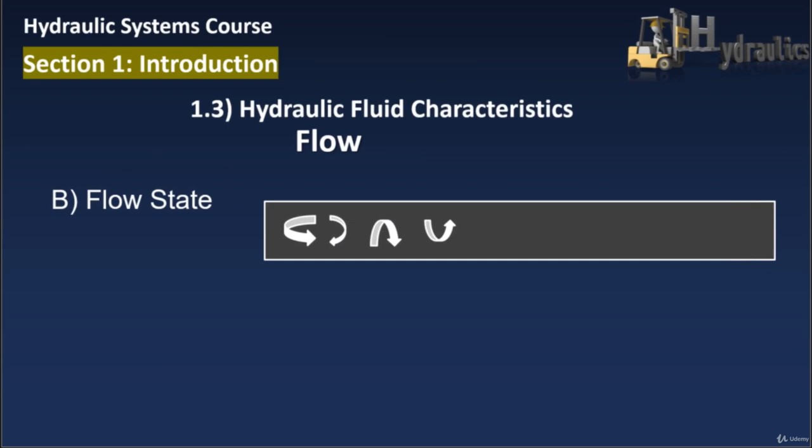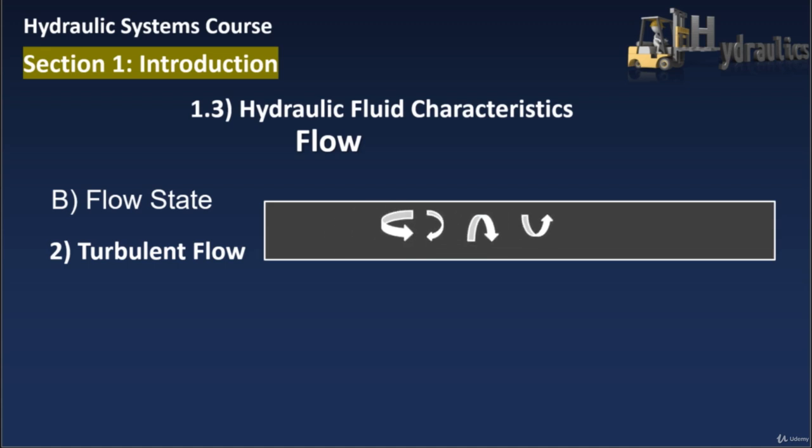The other type of flow state is turbulent flow, and in fact, hydraulic system flow often experiences more turmoil or disturbance than desirable. Although fluid generally moves in the required direction, it also travels through small conduits, cross-shaped restrictions, and small orifices, which tend to cause anything but a nice and smooth transition.